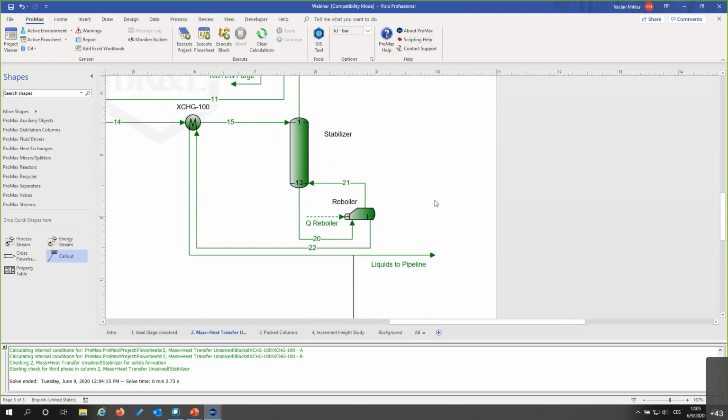But a typical application where we see a disparity between the operating plants and the assumption in engineering is, for instance, sour water strippers, because the range for sour water strippers you would find in literature is somewhere between 33 and 50%. First of all, this is quite a wide range, right? And second of all, I completely understand that engineering companies in most cases would rather stay on the safe side of things and decide to go closer to 33%.